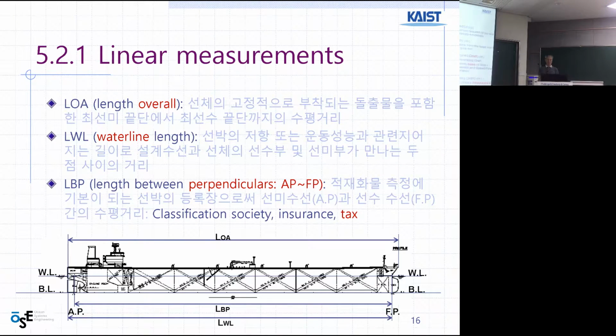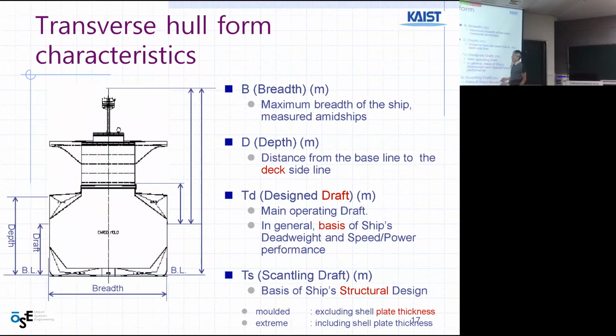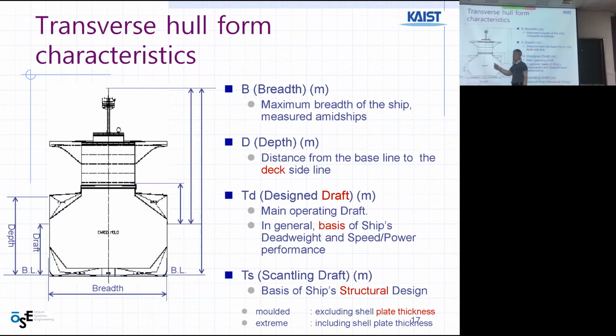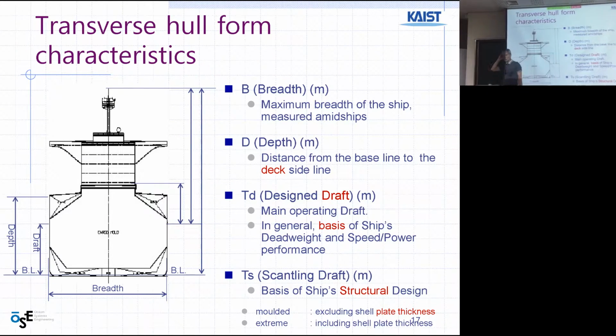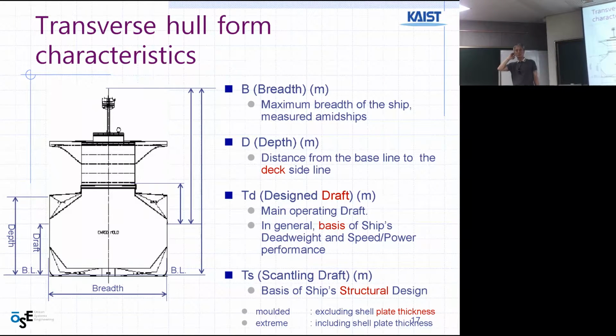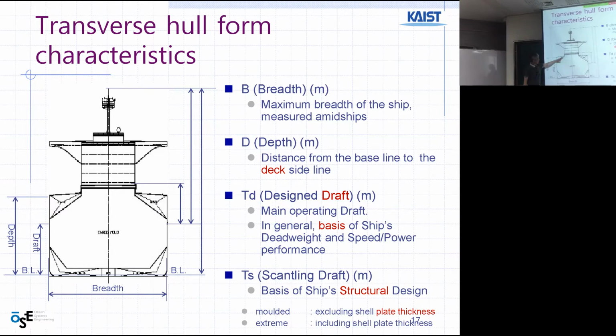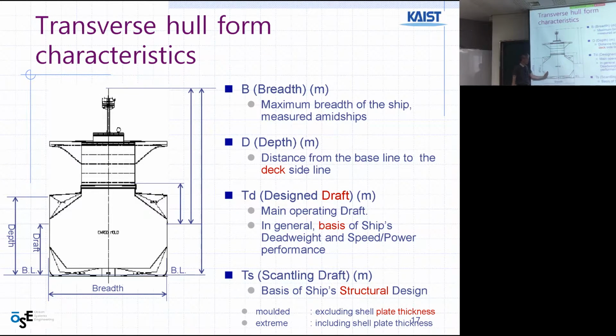Right, structure. Transverse hull form, right? Transverse midsection. And this looks like a bulk cargo ship midsection. Bulk carrier: grain carrier, coal carrier, or ore carrier. Why? Because of this shape. I noticed, you may not notice. This is good for grains, right?